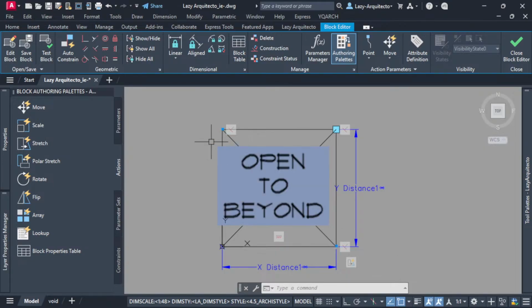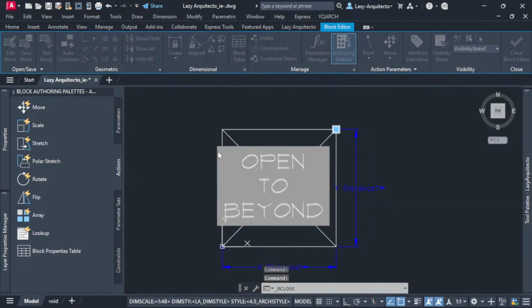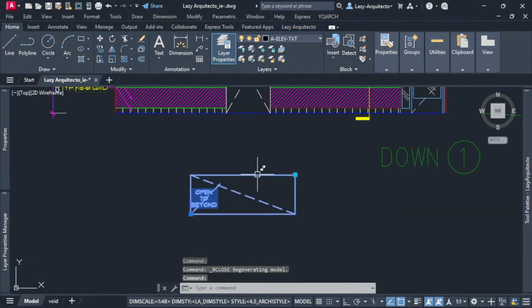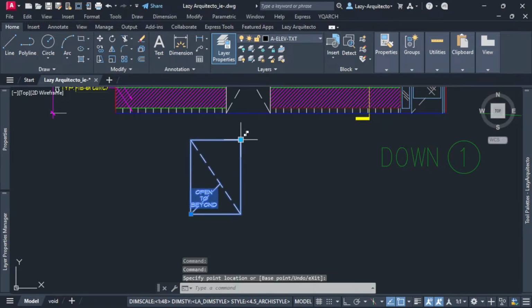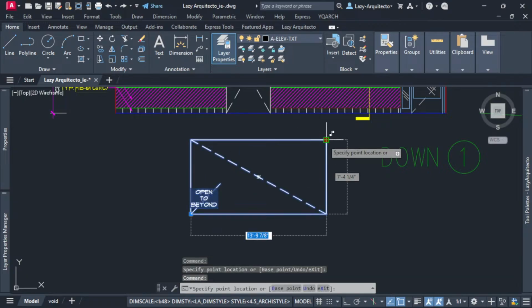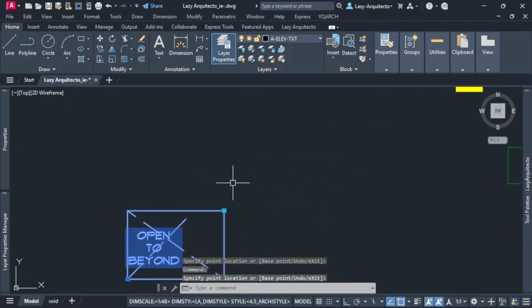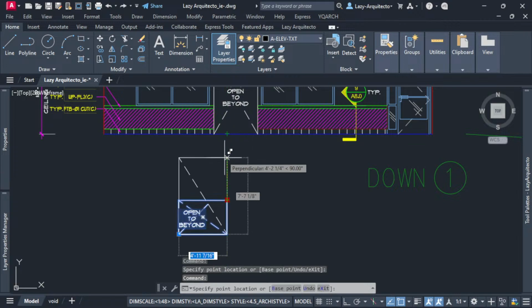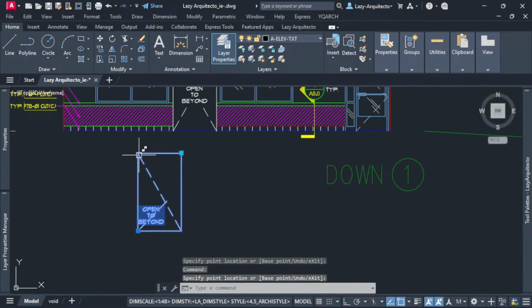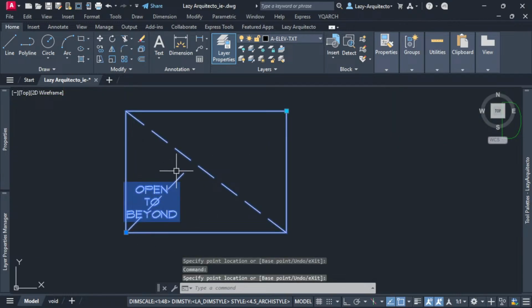one individually. So I'm gonna go ahead, and before I do that to the other line, I'm gonna test it. Save the changes. Gonna go ahead and stretch. Great, everything is working beautifully now. Not everything, but the line that we applied the coincident constraint to is working beautifully. So let's apply the same for the other line.